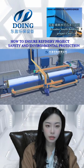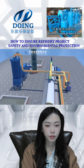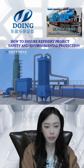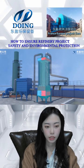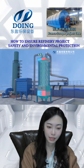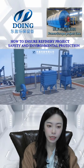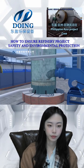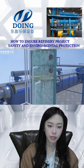And then this is the desulfurization system. The 3 devices. The first one is the air-cooled cooling device here, which can replace the water cooling to lower the temperature of the smoke that we need to release. And then the second, the post-dust collector to remove the dust from the tail gas, the flue gas. And then this is a glass fiber reinforced plastic desulfurization tower. This flue gas will be cooled below 120 degrees when entering this part.